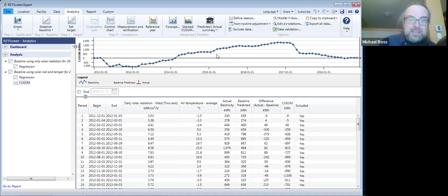I can see that the system's slope of this line is pretty stable for about a 3-year period, ending on Valentine's Day 2017. So it goes back to here to March 17th, 2014. This period, we got a pretty straight line. And furthermore, it's a line where the actual performance is exceeding the prediction. So things are going well for the system. So I'm going to assume that this represents stable, correct, no fault operation of my system.